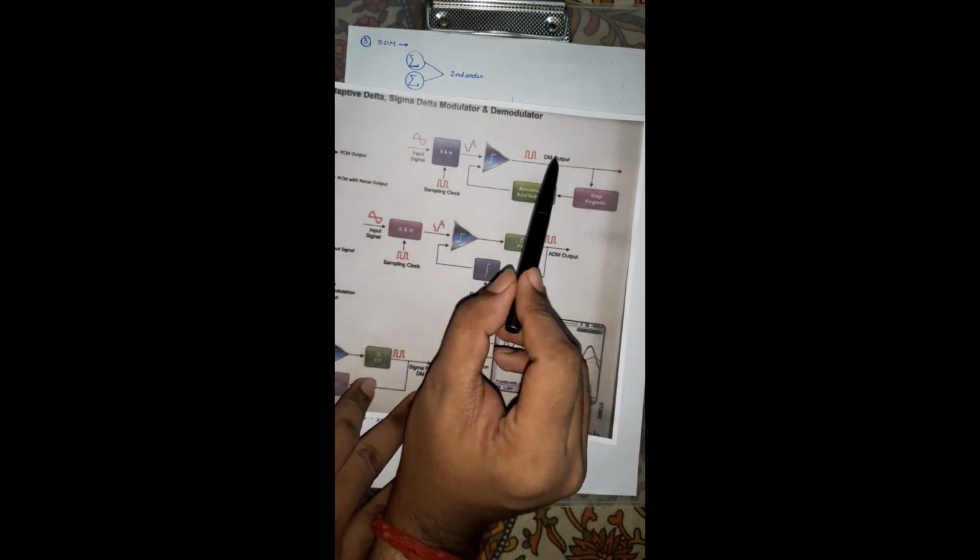So look at DM first. At DM, whatever I have told, that is the delta modulation. The input signal will be sampled by a sample and hold circuit that I have already shown you. And after the sample and hold circuit, according to it, the codes will be generated, and you can understand this signal right now, because this signal is nothing but the signal that has the constant TS, the constant sample time, as well as the constant step size. This is actually the DM signal.